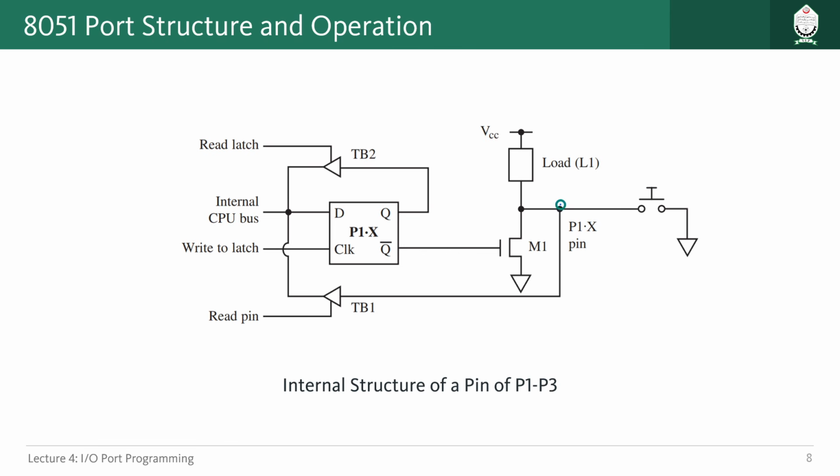That logic high will go through here and will be latched onto the internal CPU bus with the help of this tri-state buffer, right? And whenever you press this push button, directly this ground will come here. But even if this is a shorted path, both of them are ground, so no issue will happen, and we are going to get the logic 0 signal through our tri-state buffer to the internal CPU bus. So basically, using these mechanisms, you can at least avoid the damage of our MOSFET.